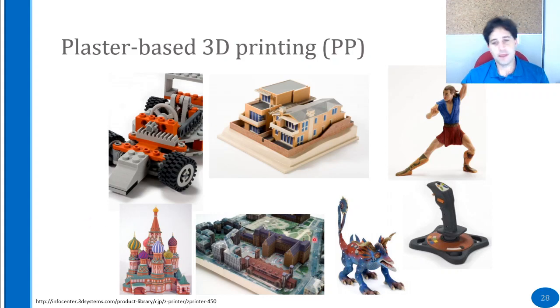Of course, there are many problems with this technology because the granularity, the resolution that you can get to depends on the size of the grains, and this is still a very chemical process that is as strong as the binder. These are usually not very strong parts, and I personally see less of these technologies lately. These printers are losing their popularity in favor of other ones. But still, you can find this in professional high-end machines.